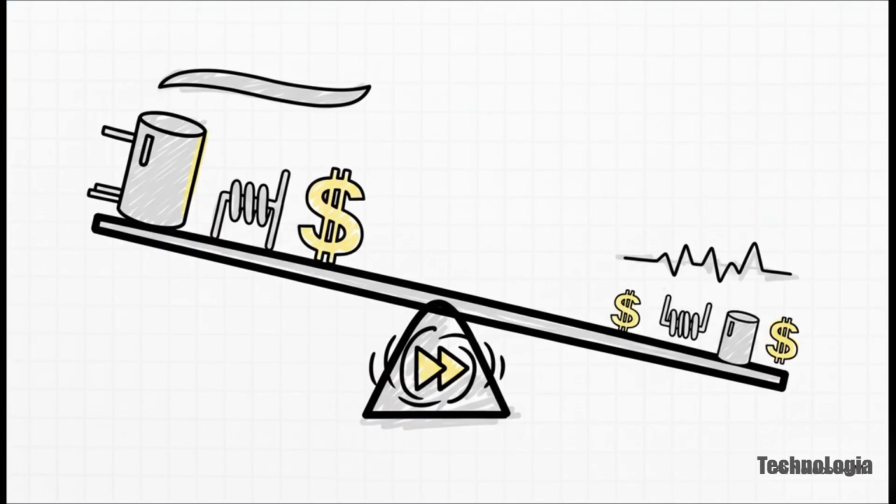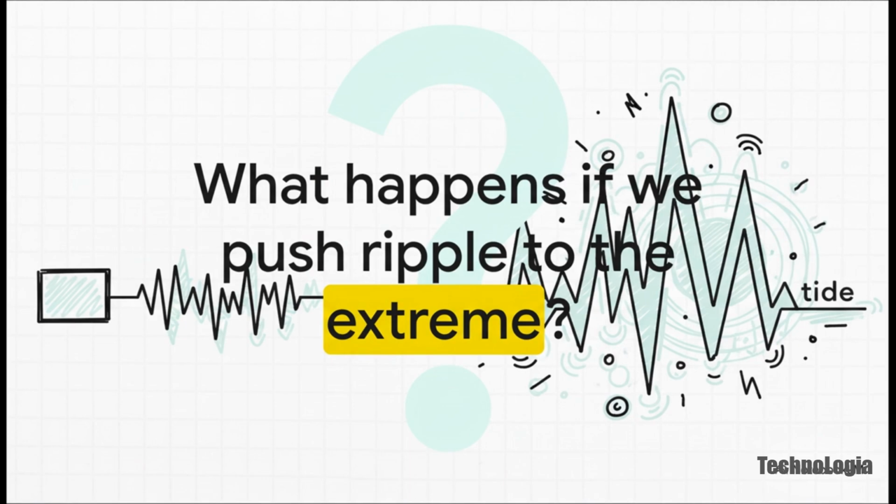This puts engineers in a constant tug of war. If you want a super stable output with almost no ripple, you have to use big, bulky, and expensive components. But of course, we all want our gadgets to be smaller and cheaper. The way you get there? You switch faster. The higher that switching frequency, the smaller and cheaper you can make the components. And this is where we get to the heart of it.